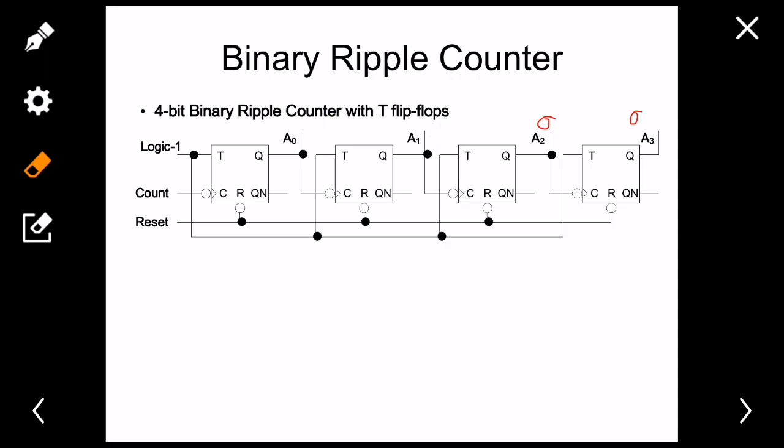So this is a 4-bit binary ripple counter. Many times we need a special type of counter known as a BCD ripple counter. A 4-bit binary ripple counter should count from 0. As we are seeing, I have taken negative edge triggered flip-flops, so it is basically an up counter. It will count from 0 to 15, right? But in BCD we have 0 to 9.